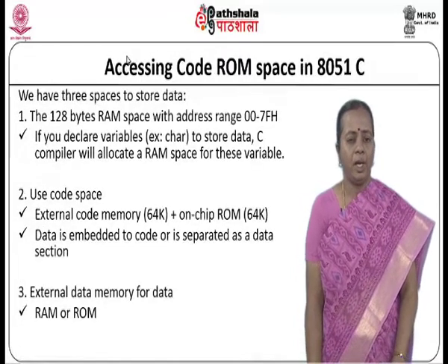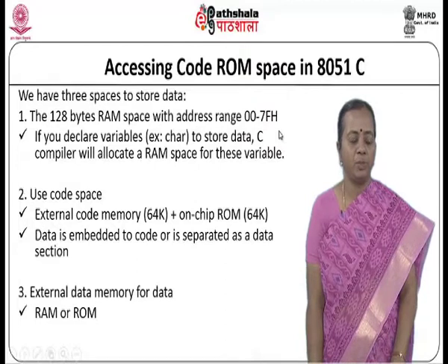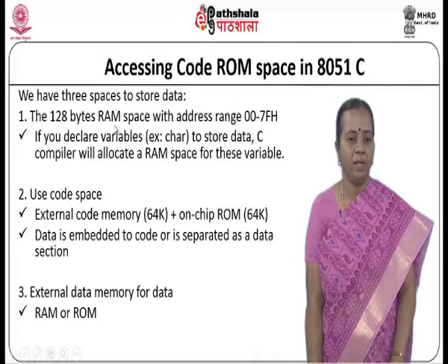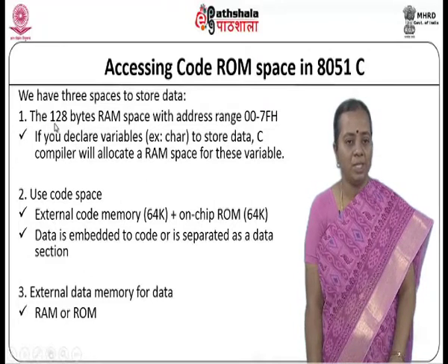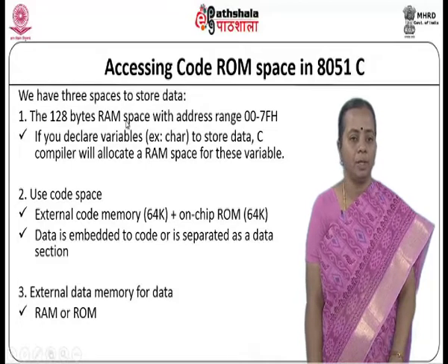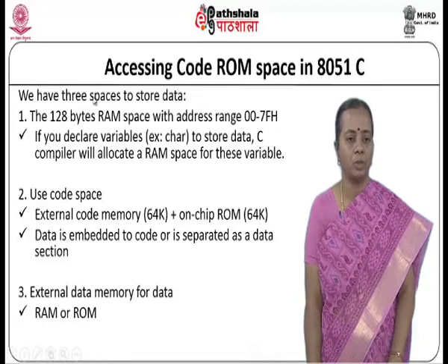When you are looking at this kind of operations, we will be looking at the memory space also. We know very well that with the 8051, we have only the RAM space of 128 bytes. So, at the maximum I can store only 128 bytes, but sometimes it may not be possible to store within this particular area. So, by that time we can use the code space also.